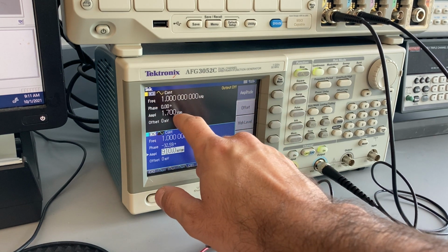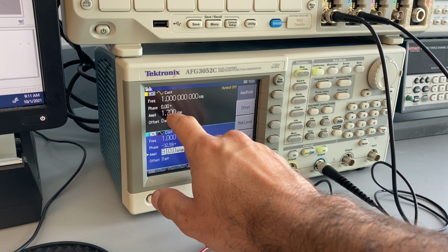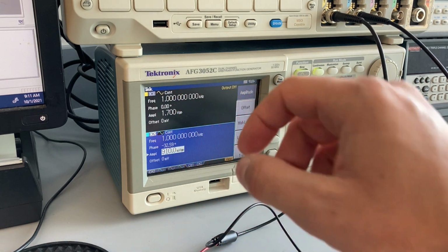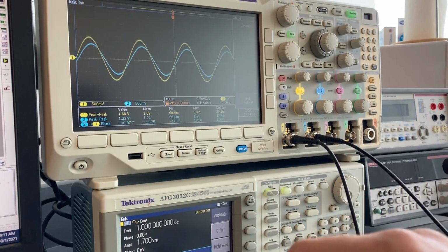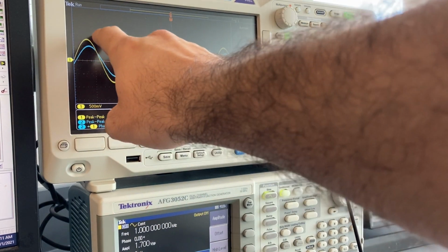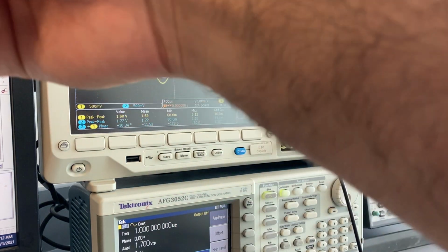In this case, in the very first circuit, rather than inputting 2 volt peak to peak, I have 1.7, right? What I do there is that I make sure that when I connect the oscilloscope, in order to get to the right apparent voltage, all I have to do is look at what the oscilloscope has as the peak to peak function and line it up with what I need.